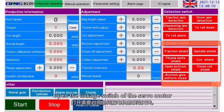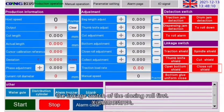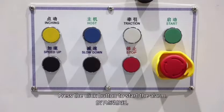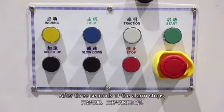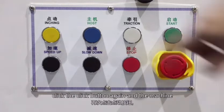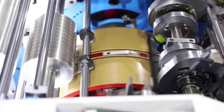Open the linkage switch of the servo motor that needs to be enabled, and do not open the linkage switch of the closing roll first. Press the click button to start the alarm. After 3 seconds of the alarm stops, click the click button again, and the machine operates normally.